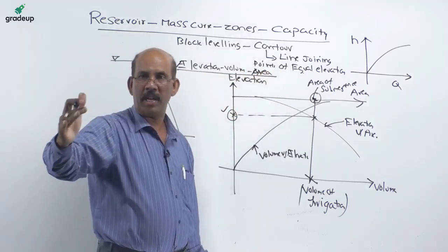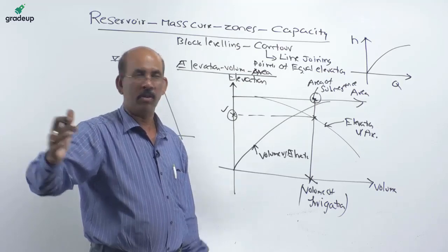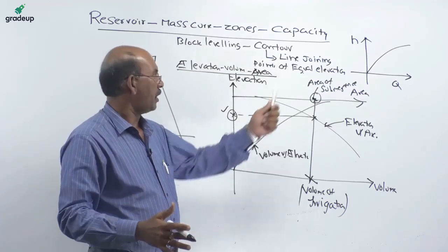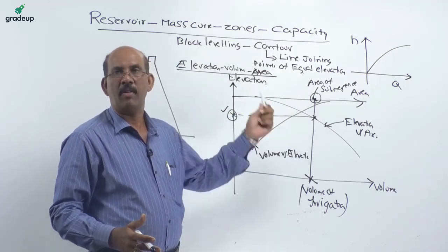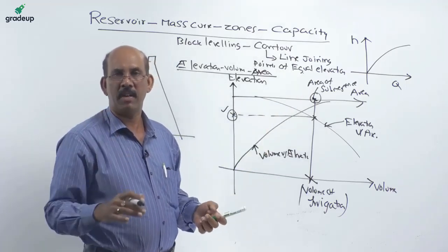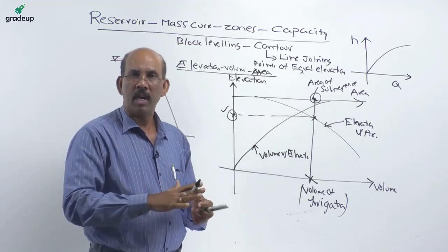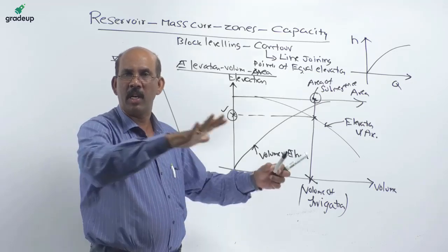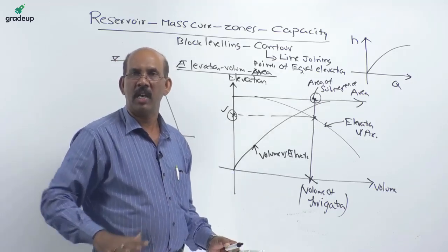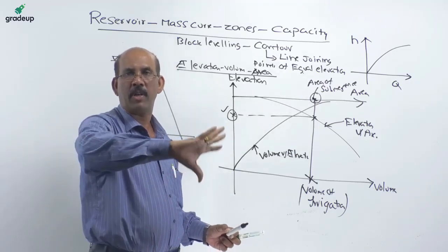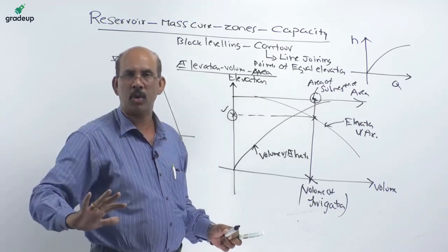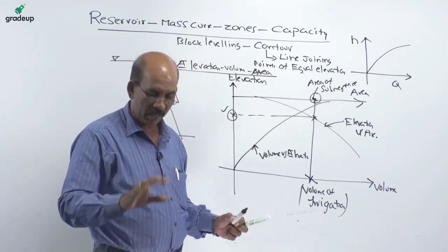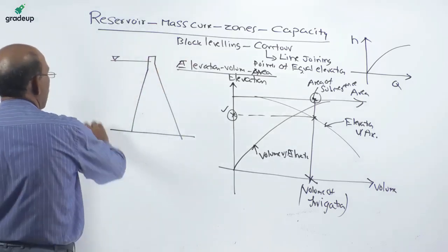Elevation, volume, area, the capacity curve is to be first drawn, and using our demand and the stage discharge curve, we can plot the height of the dam. So, this curve is required to represent the ground situation, that is, indirectly how much water can be stored at this location and how much water is required, and accordingly the height of the dam is decided.